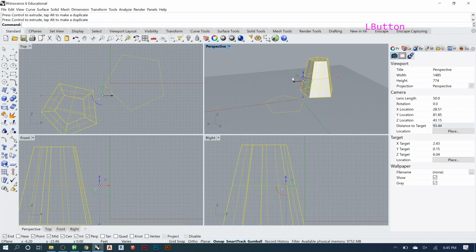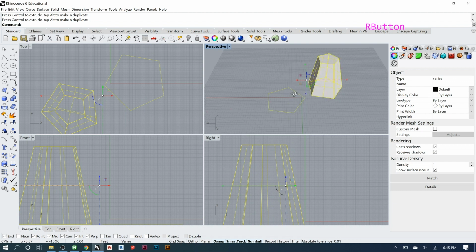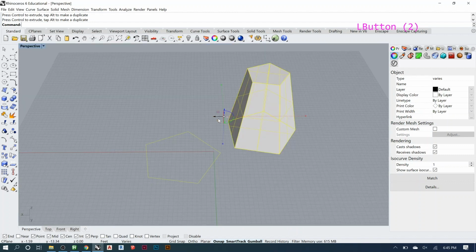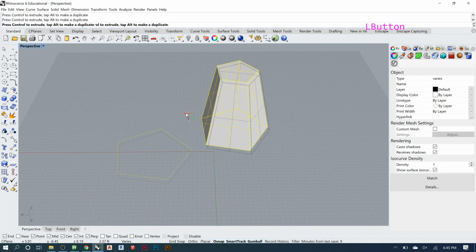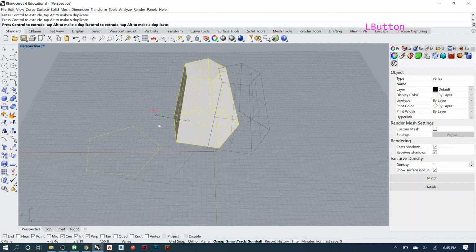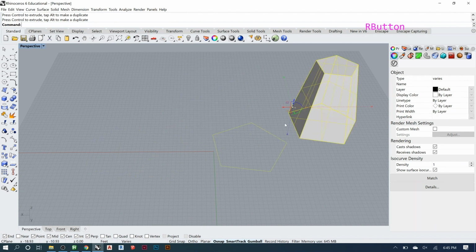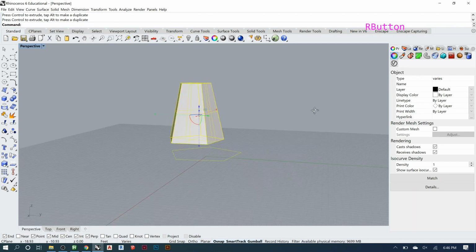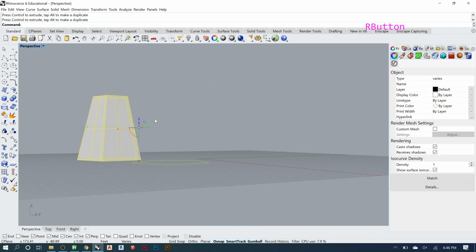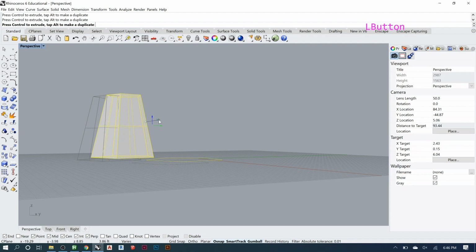As you move around, you get these little squares, and they're colored in the same colors as the axes that they represent. So this would let you move in both green and red, but not vertically. Your object would be locked to that plane, but it would still move around, and it's always going to stay flat. Whereas if you move down this way, we can move it in that plane, but it's not going to come towards us ever. That's just something to be aware of.